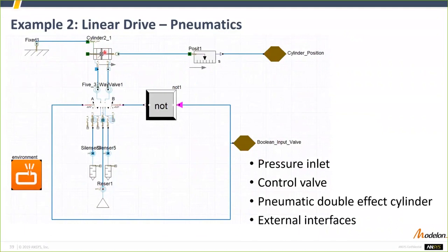The cylinder is modeled here with some cushioning, and you have the valve here, which takes air either from a reservoir, which takes it directly from the environment and compresses it at the given pressure, typically 7 bars, and gives it back through the silencer, which also has a restriction inside, because the silencer usually has a restriction to reduce the noise generated at the output when releasing the air, typically into the environment.